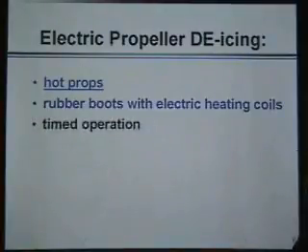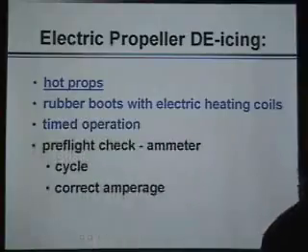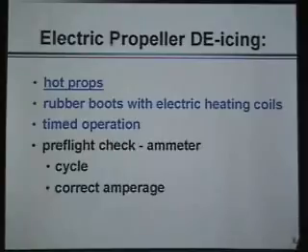I already showed you the timed operation, and the best way to check to see if this system is working is similar to that of the pitot-static heating: turn it on. You'll probably have the engines running by then, but you're going to check for that cycle to see if the appropriate amps come up on each one.